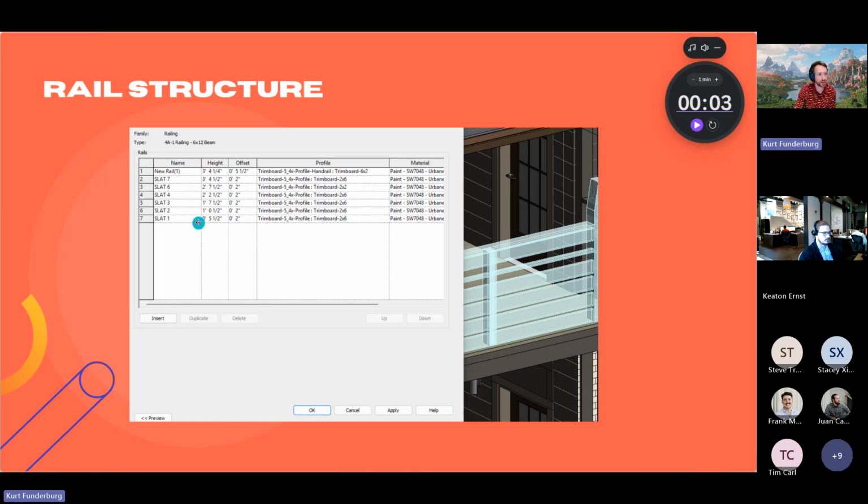But then I'm setting the height at 5.5 inches, which is the 2x6 trim that we're using. And then I'm spacing that, counting 5.5 plus 5.5 plus the gap. So you're seeing there's the 5.5 plus the 5.5, and then there's a gap number right there that's pushing it up. And this offset is interesting because that's allowing us to justify where it's sitting within the plane